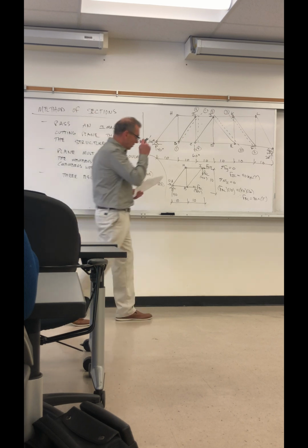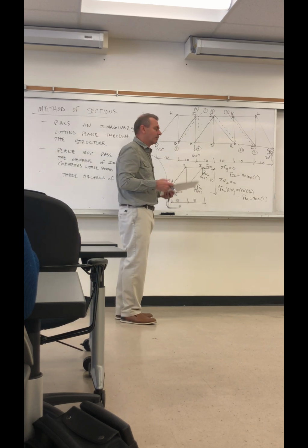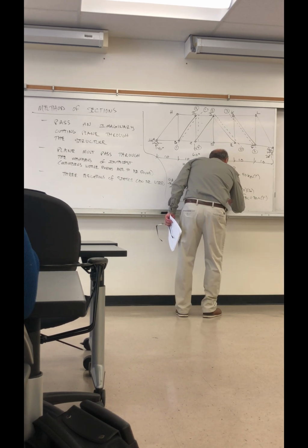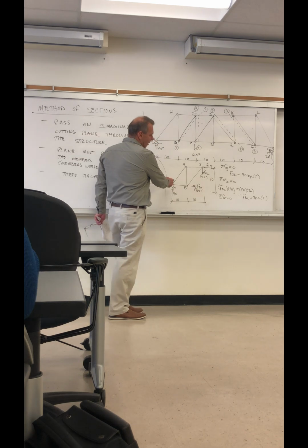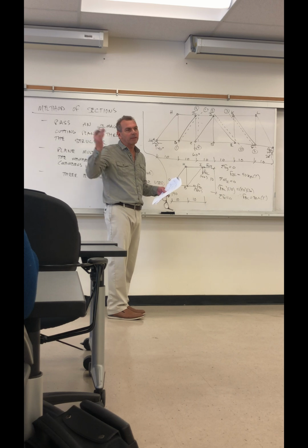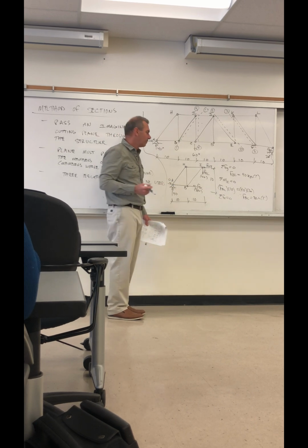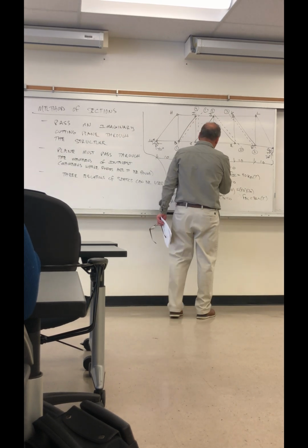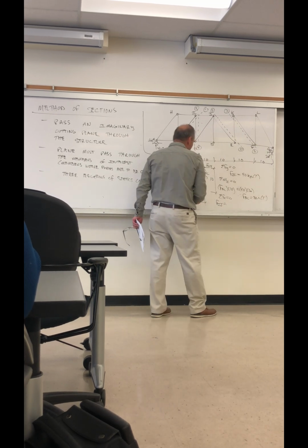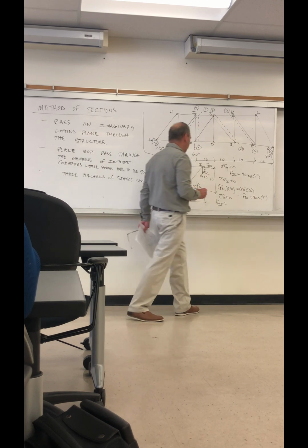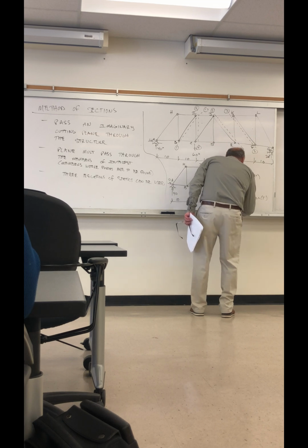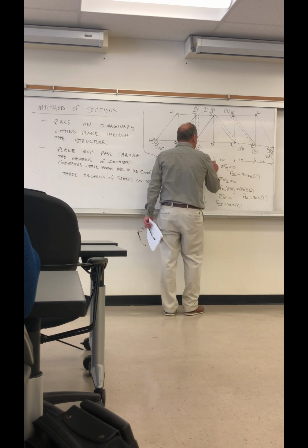Then the last equation available to us from statics for this is the summation of forces in the x equals 0. Now there's no force here, but if there were longitudinally, then we would have to include that. You're including the whole picture up to that section cut, the whole structure. In this case, F of IJ just equals F of BC, but in the opposite direction, 80 kips, and this is in compression.